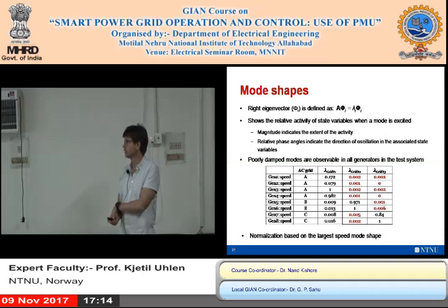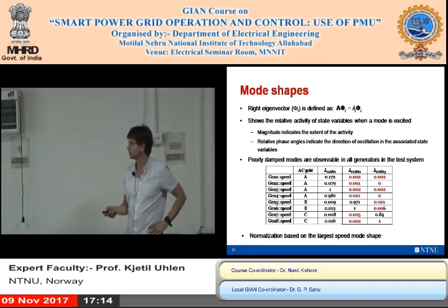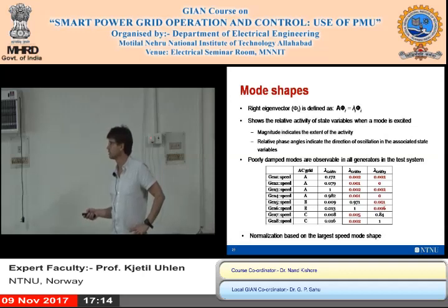If you do the small signal analysis and do time series simulation, try to do a small disturbance and look at the results, we are able to see the couplings. If we excite the inter-area mode, we can see that mode in the other system. So if you have a short circuit here, we can actually recognize the mode in this side. But the amplitude is negligible.